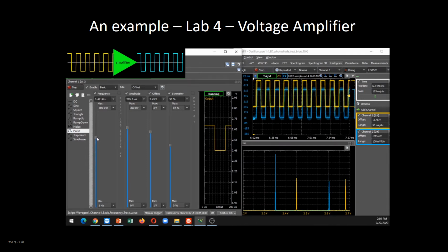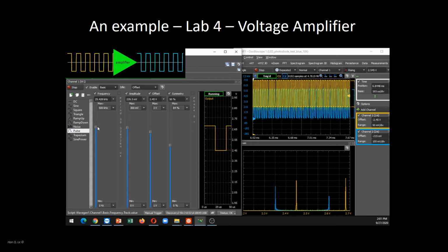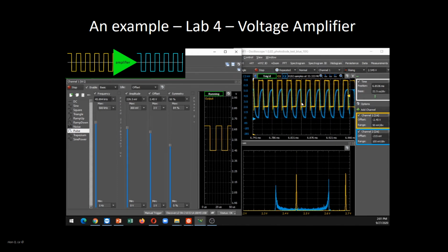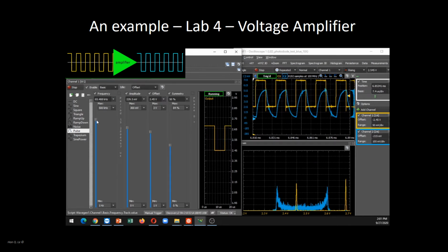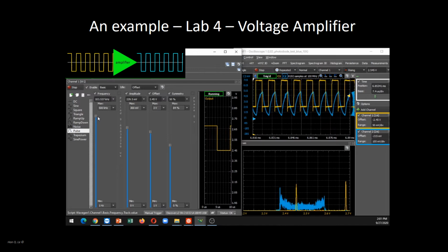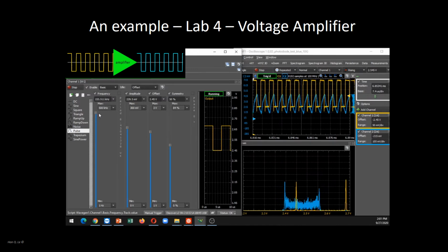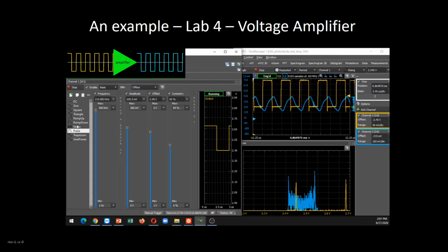At low frequency, the amplifier works as expected. But as the frequency increases, the output amplitude decreases and the wave shape becomes deformed. A purpose of the frequency response measurement is to determine the useful range of frequency of a circuit. For those who are familiar with Fourier analysis, the output roll-off at high frequency can be attributed to the vanishing of the higher-order harmonic components, leaving only the fundamental and few lower-order Fourier components in the output.